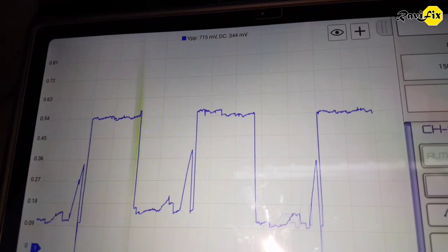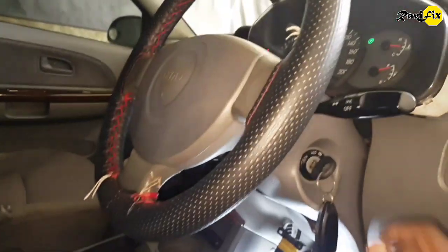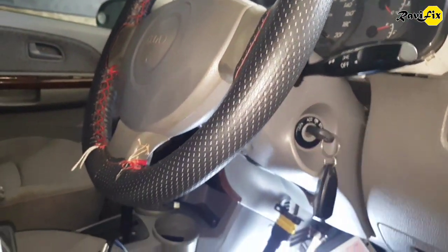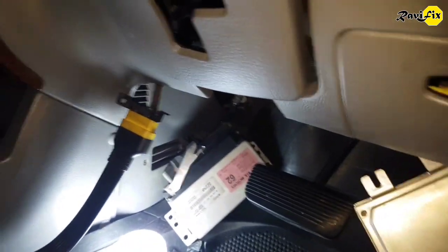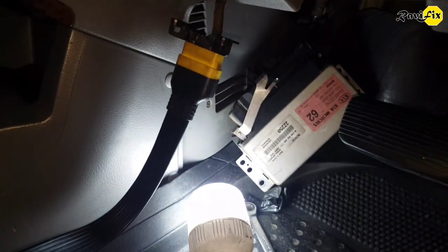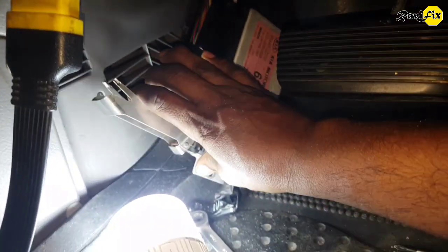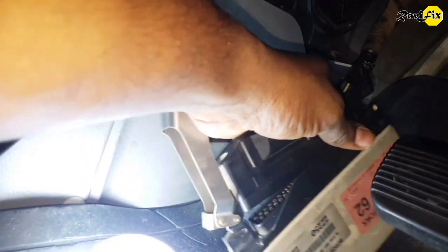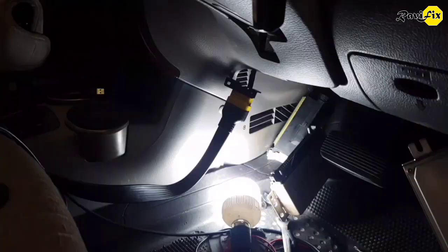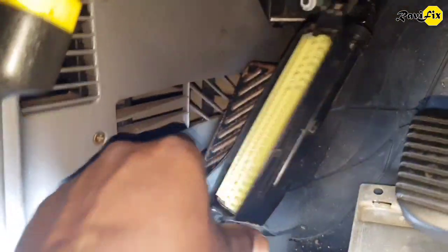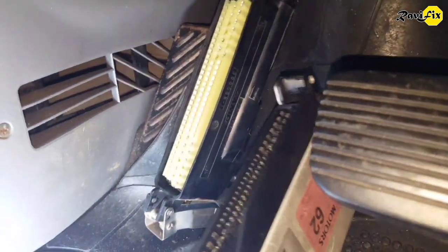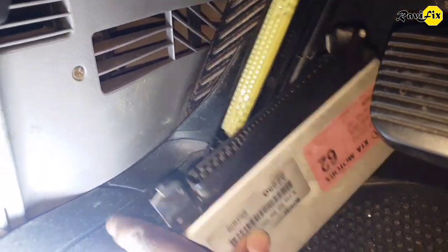As I checked, the wiring integrity is okay, so the TCM or the instrument cluster panel might pull the signal to ground. The instrument cluster panel has already been changed by the customer. Okay, I am going to unplug the TCM first and check whether the TCM pulls the RPM signal to ground. I hope this TCM removal will not be a problem to start the car. Let's see. Okay, unplug the TCM. Let's start the car and see what the RPM signal will be.